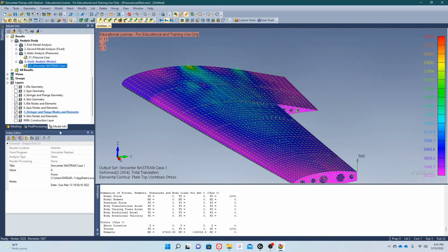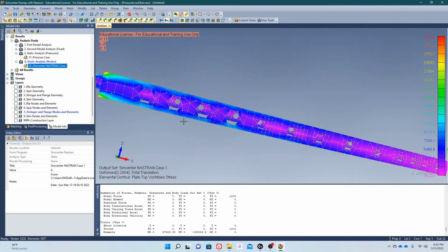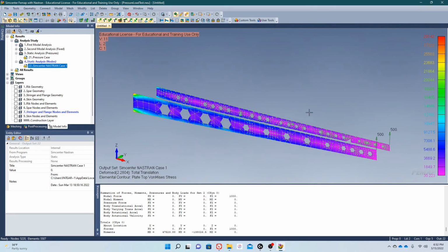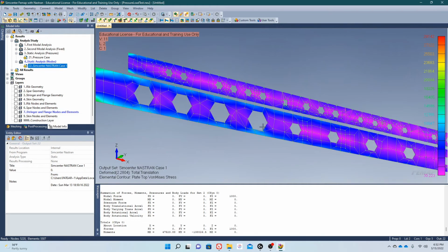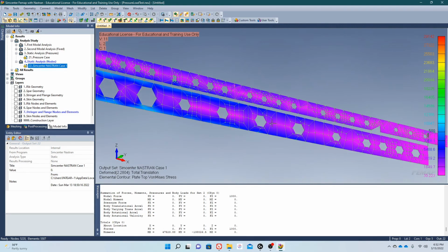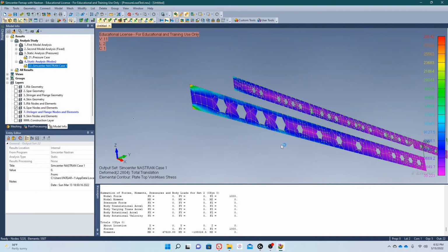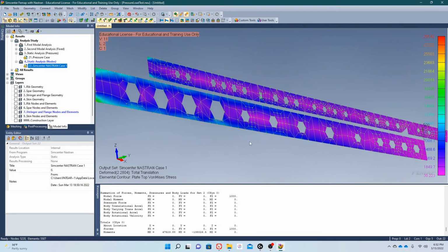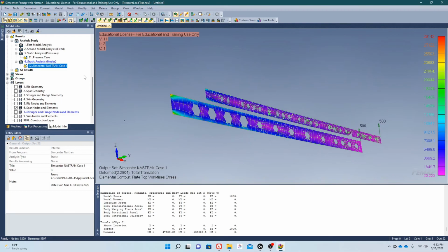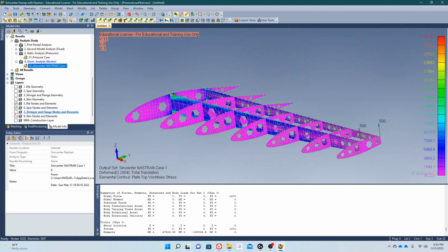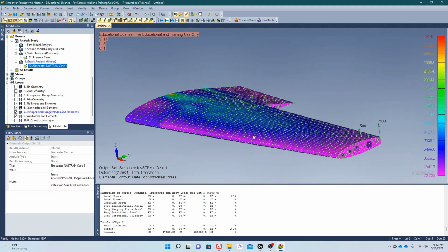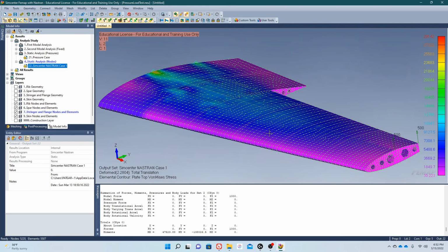And just like in the pressure case, if we look at the spars, we can see the stress distribution along these spars has very little effect because of the holes. The holes don't affect that as much as one might initially think, which is, as said before, expected and good for weight saving.